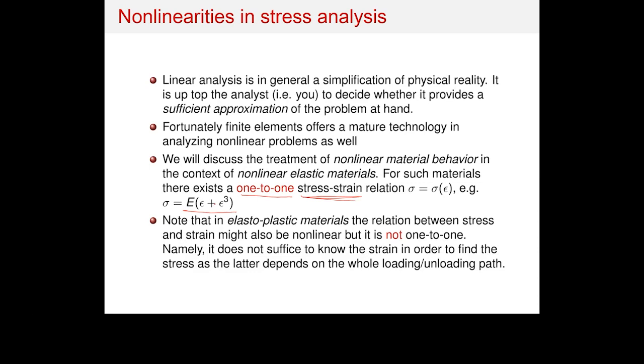All right. And there's one thing I want you to really understand: as an engineer, as a designer, you are the one to decide if your problem is linear or nonlinear. And if you decide that your problem is linear, and this is not going to be a fit approximation, this would mean that your design would face severe challenges, probably failure. So be very careful when you make your decision on working on a nonlinear problem or a linear problem.